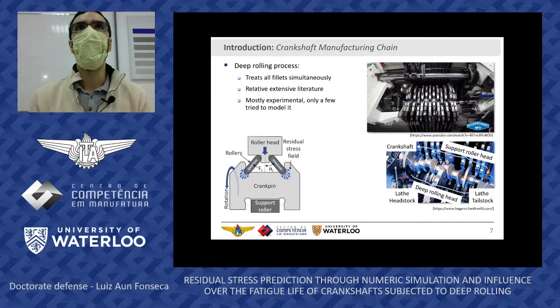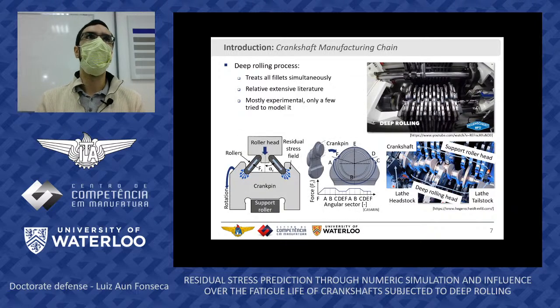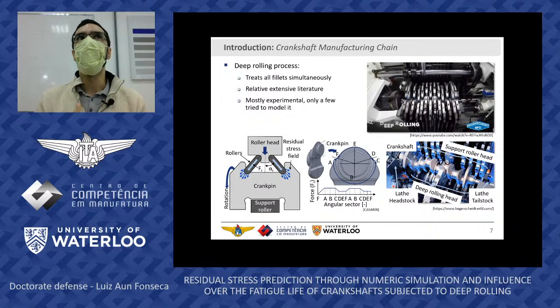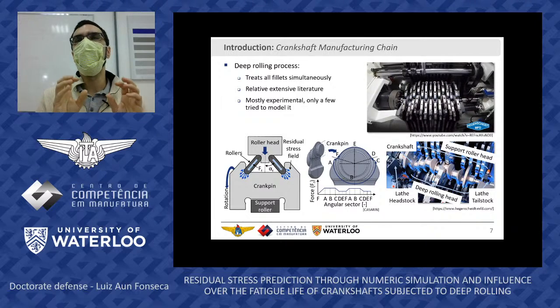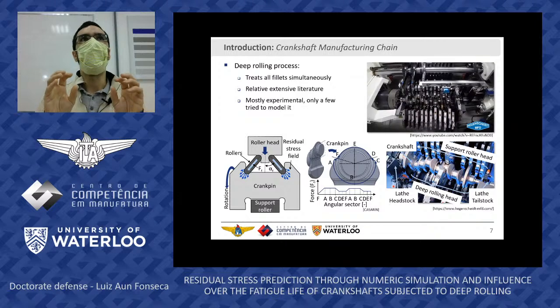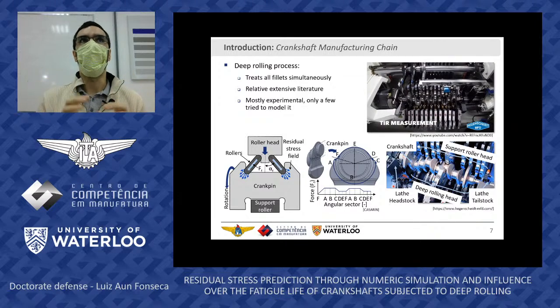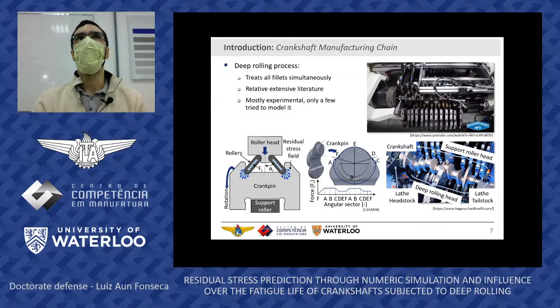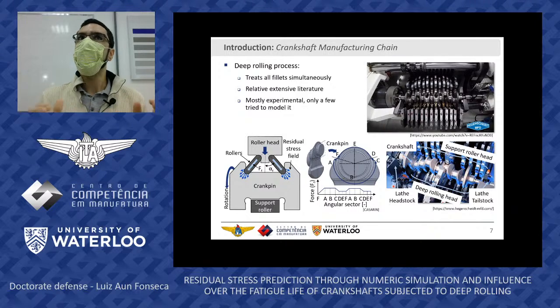And this process, just to explain a little bit better, the force is applied through the roller head down to the angled rollers, specifically at the regions of the fillet radii. We're creating this ovalized residual stress field, which will be applied not constantly, this force, but alternatively.